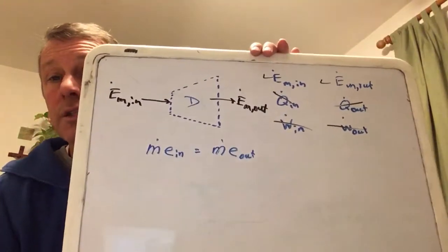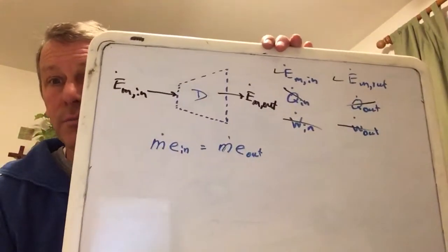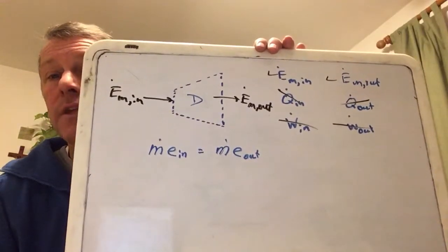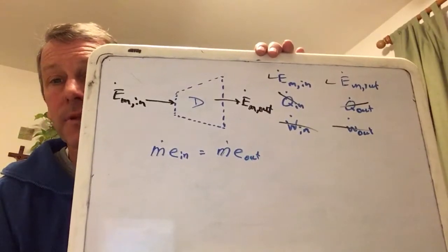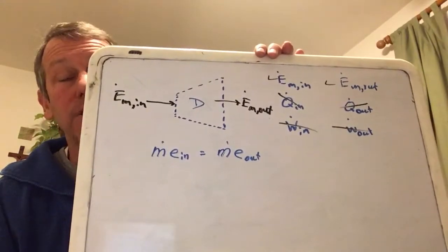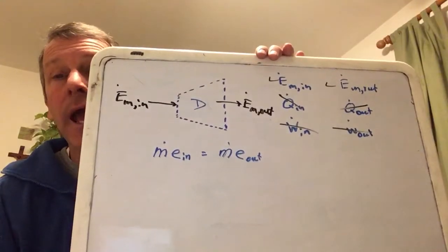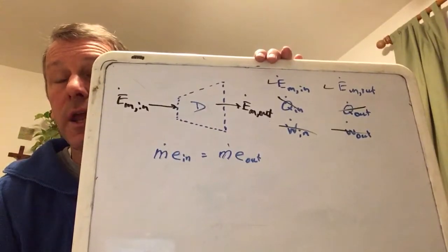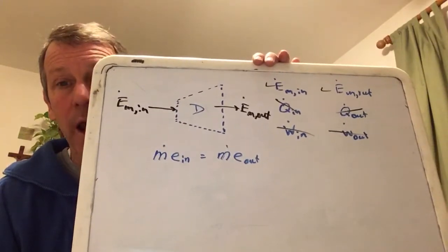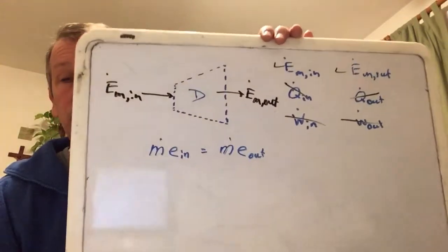What I'm going to ask you to do is keep moving through this equation and see if it will allow us to meet our goal of figuring the temperature at the outlet. We want to do any algebra or simplification we can first. So first, think about the m dots and how we actually write E, specific energy, for a flowing fluid. Let's see what the next line looks like. I'm going to use 1 and 2, 1 for in and 2 for out.